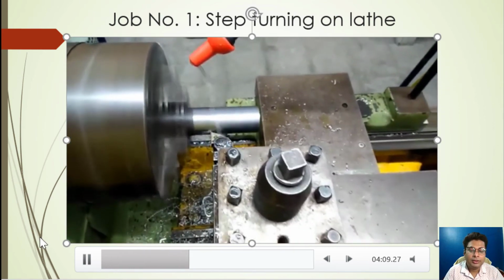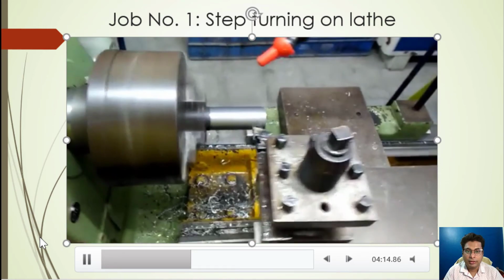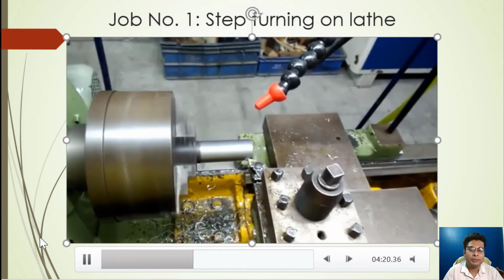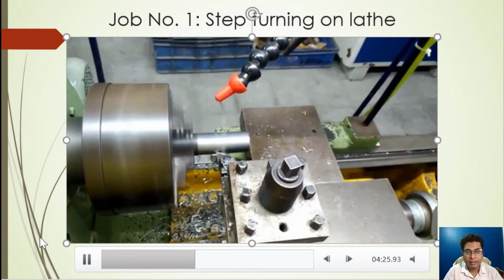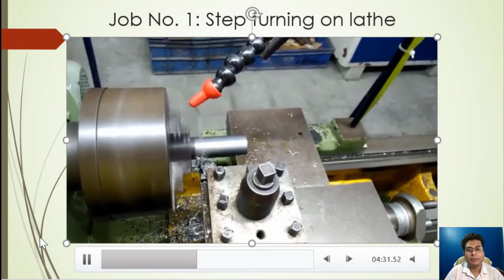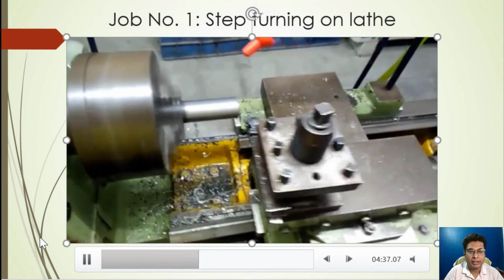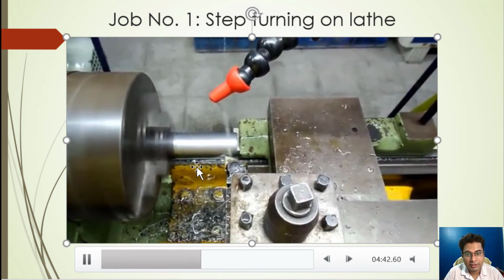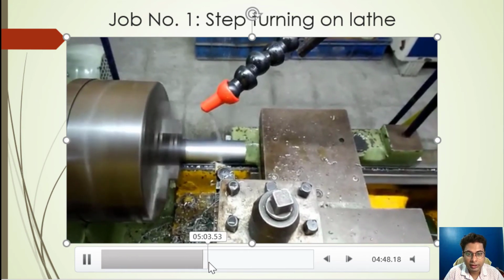Actually, if we need to reduce, suppose 6 millimeter radially, in radius, we can't perform that operation in one single pass. We need to give multiple passes in order to perform that. If we try to do it in one single pass, that will damage the tool severely and the tool might break. So tool failure will occur. See, multiple passes are being given in order to get the required dimension.